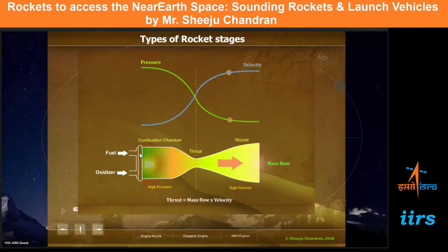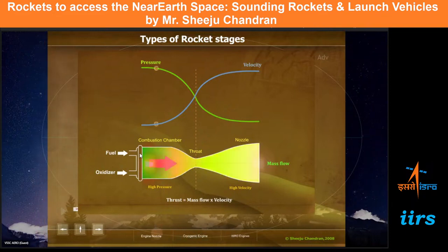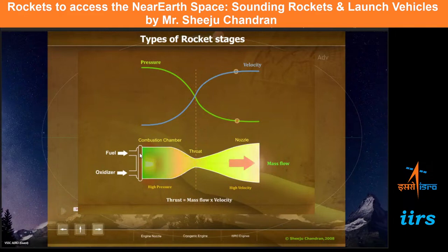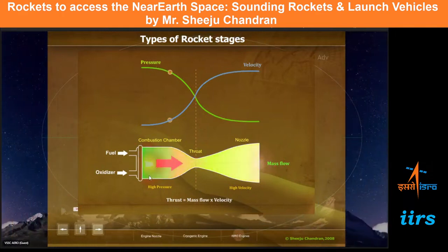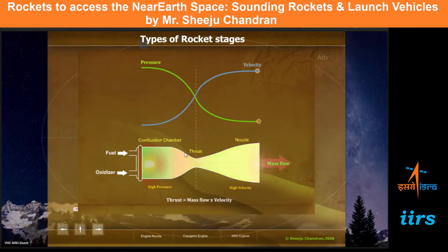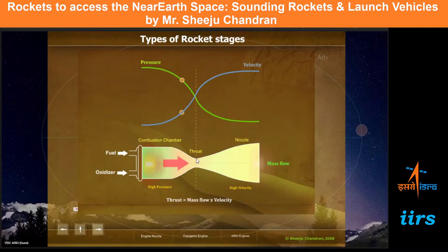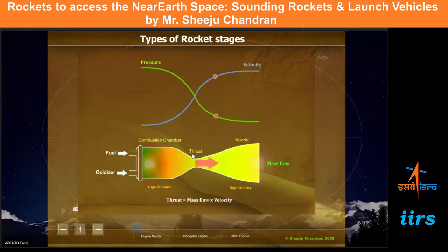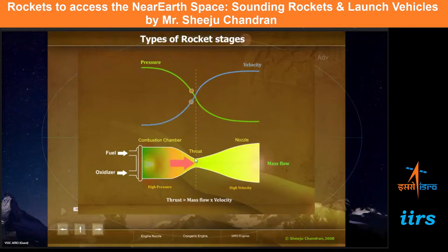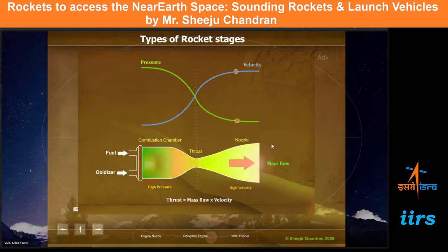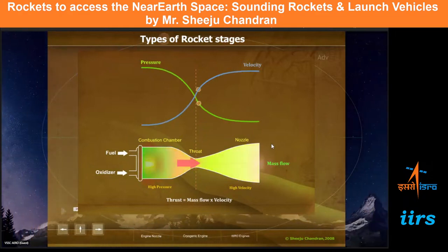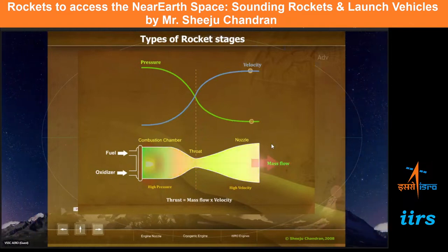The basic principle is very simple. It's called a nozzle. Or to be precise, a rocket uses a convergent divergent nozzle. If you see the picture, you can understand this is where the thrust is produced. Then there is a convergent portion, right, where the mouse cursor is. There is an area where this convergence reaches its maximum. Then it diverges. So you have a nozzle with a convergent portion, a point of minimum cross-sectional area, which we call the throat, and then a divergent portion.